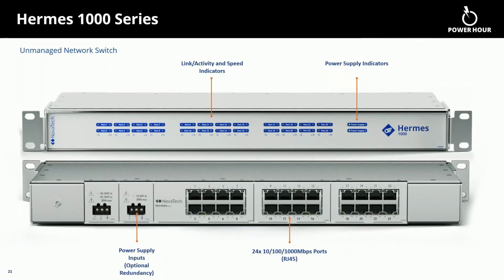But if you're starting to go through a lot of routing, you want to have those offsets, and you'd probably move to the 2000. So that's my understanding of, yes, it can handle it, but the PTP transparent edge clock functionality exists in the 2000. The 1000 that you're looking at here can work, but doesn't have the managed smarts in that area. So it would work though.